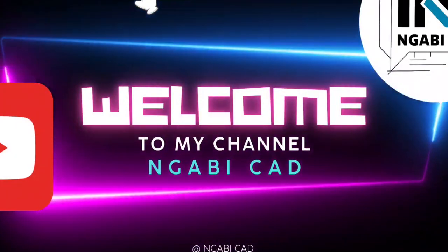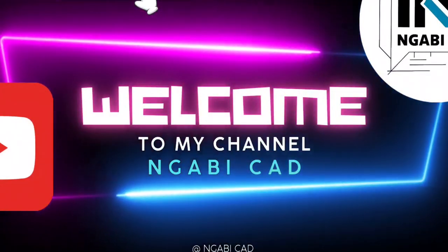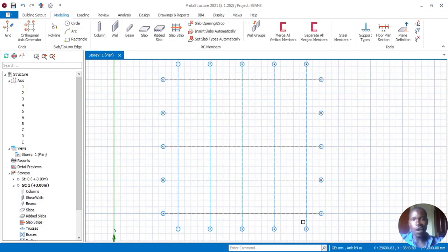Secondly, the other structural elements in ProtaStructure are beams. Beams connect to columns, which we drew last time. As you see, the beams obtain the load from the slabs and forward it to the columns. So for today, we are going to draw beams on the columns we drew last time.